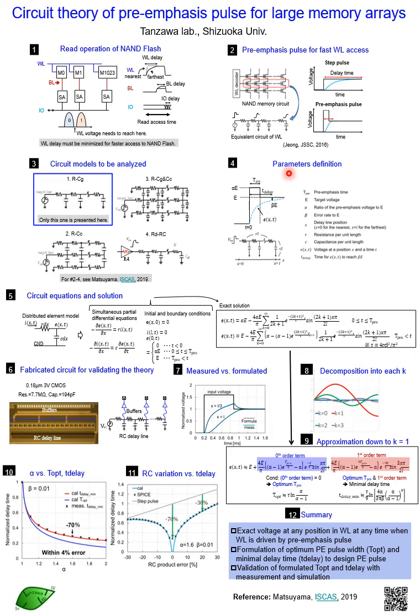This technique was already presented in the early 90s, but recently the NAND flash, 3D NAND flash, needs to use this technique because the RC delay time of the word line has been prolonged significantly compared to the 2D NAND flash.